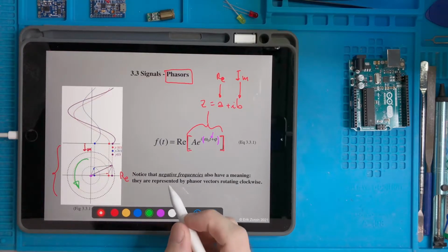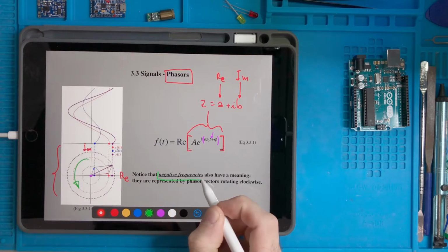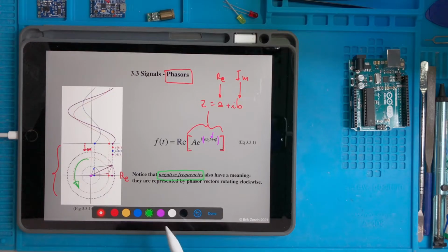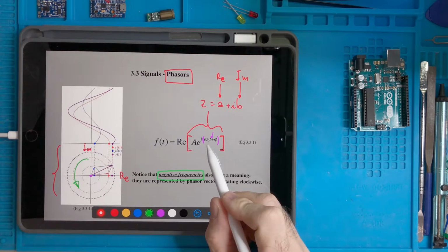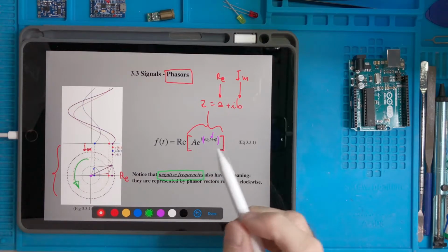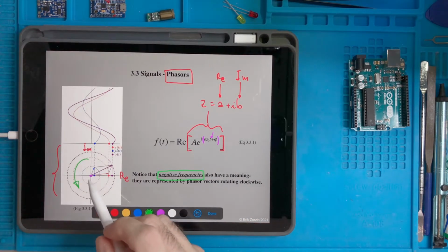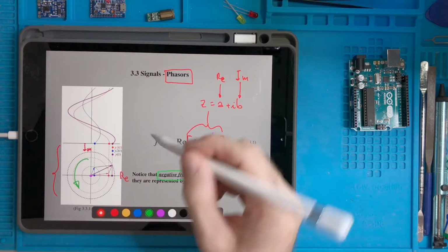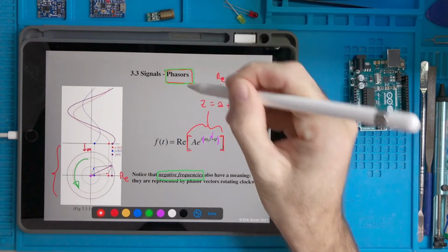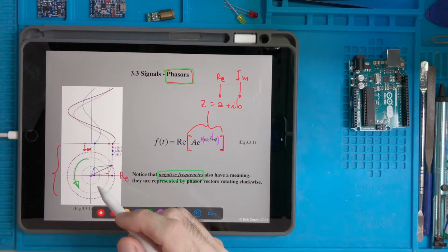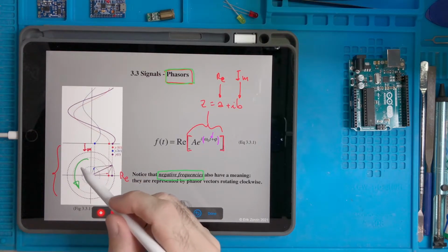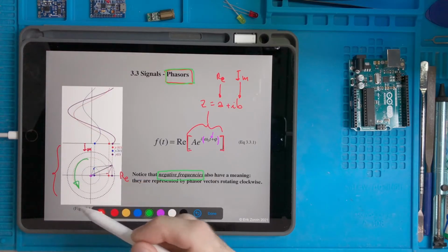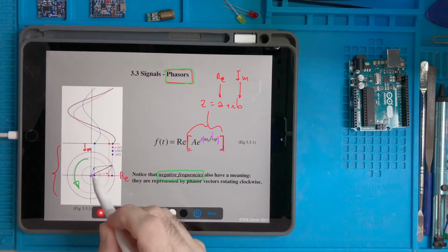And notice from the very beginning that there are also negative frequencies, meaning that if you put minus omega 0 here, omega 0 is just a number, you obtain vectors, which we call phasors in this context, that rotate at the same pace, let's say the same speed, but with different verse of gyration. And A is the amplitude.